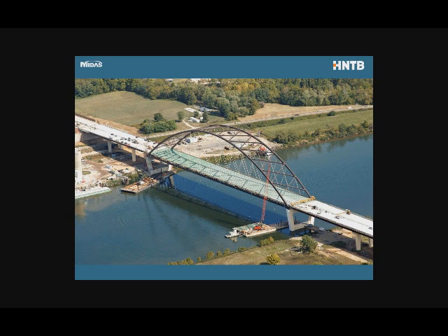The only thing to watch out for, as I mentioned earlier, is how sensitive arches are to non-uniform loading. So that's something to look out for, to make sure that you don't get unbalanced load. Blennerhassett was very non-sensitive to that, so they just did it in 3 big pours, starting from one end moving over to the other end.